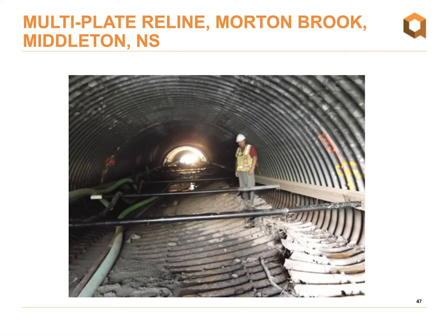As you can see, this end was in much worse shape than the other end. The invert had corroded and began to protrude upward into the waterway. Nova Scotia Transportation and Infrastructure Renewal, who I'll refer to from now on as TIR, had installed some horizontal cross bracing at 3-meter centers to attempt to stop the structure from deforming any further.